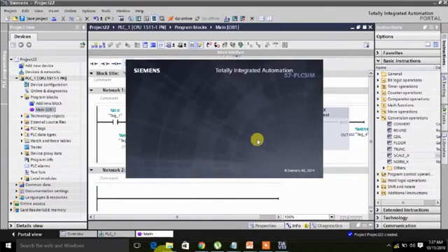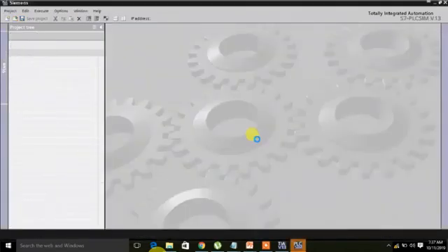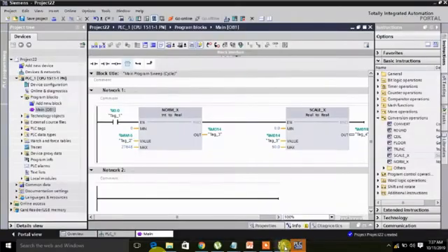When you are doing it in the field, in place of MW10 you can use your analog input data coming from the field, that may be your temperature transmitter or your pressure or flow or anything that you are using physically. So you can use MW10 in replacement of that. Here we don't use any real analog, so we are using MW10, and we will move it accordingly and see how the output changes and what value will come. That is actually the scaling.